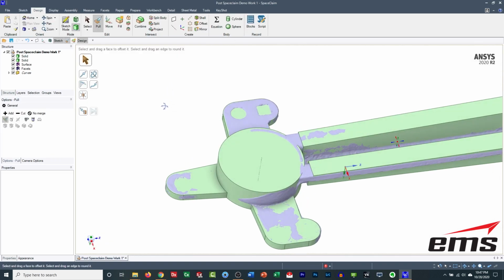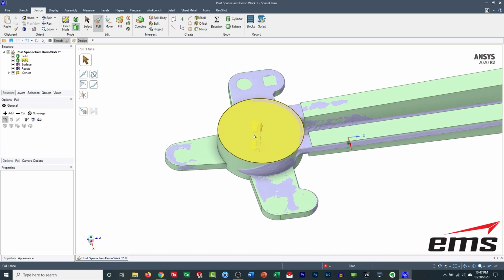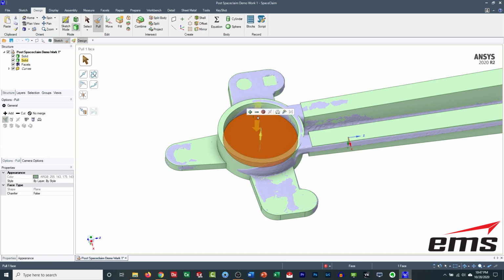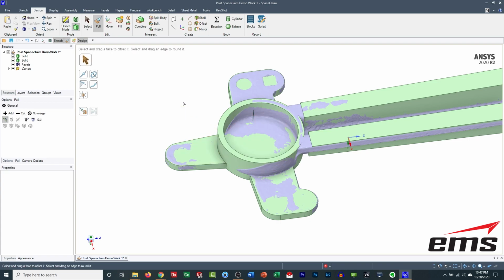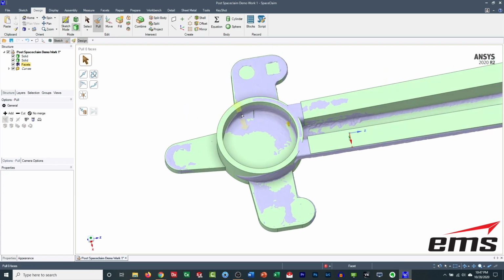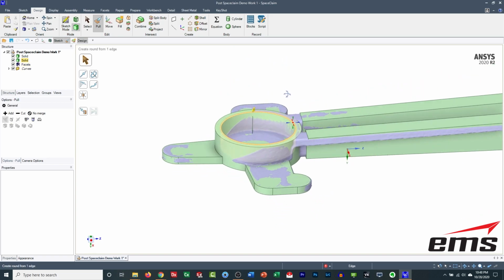And we'll hit end. Now it's kind of sitting inside there, so what you can do is use, in the case I have it set up, the control and then the wheel button on the mouse, and that'll cycle through the layers, so to speak, to find what you want. So let's go up first. We're going to do a cut, and we'll go up to this face. So that's going to cut it away that way. But then I need to do it again, still cutting, and go down so we get it right at the bottom, because we moved up to get that section. So we extruded it both directions.